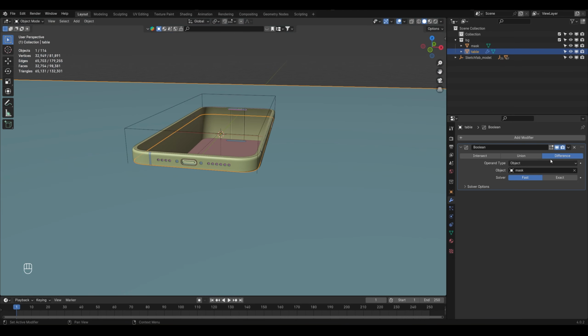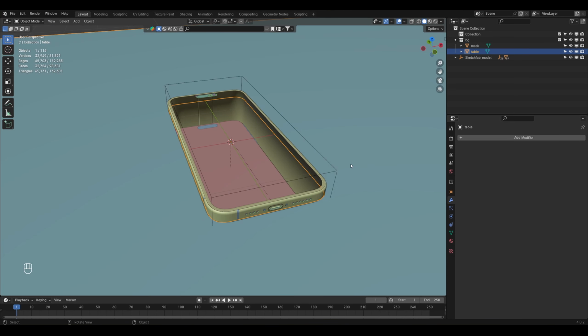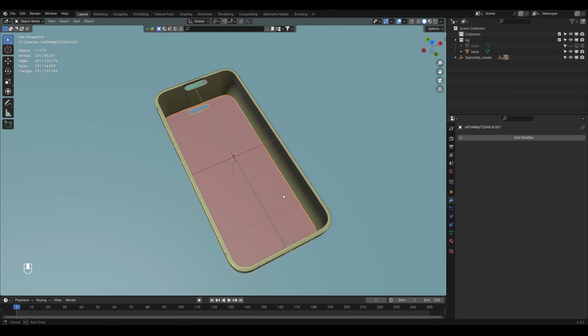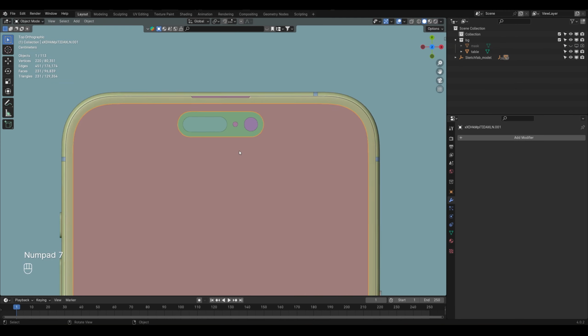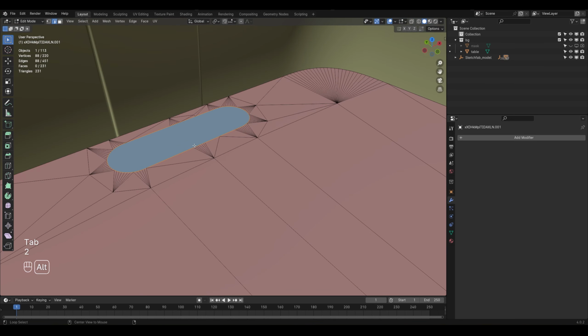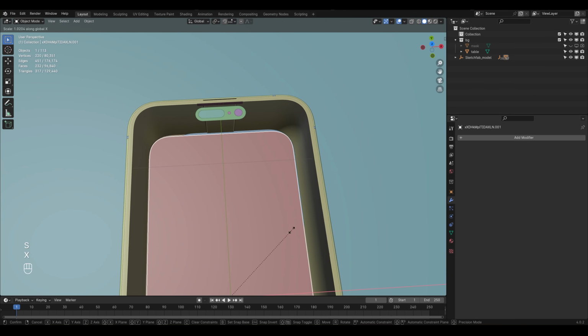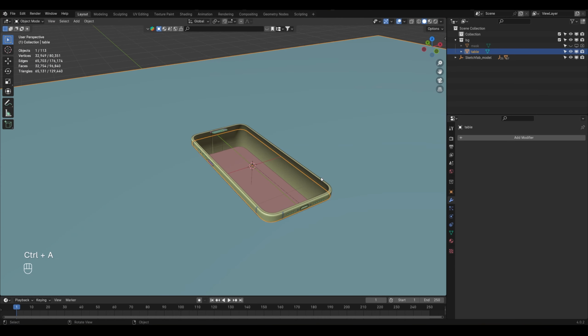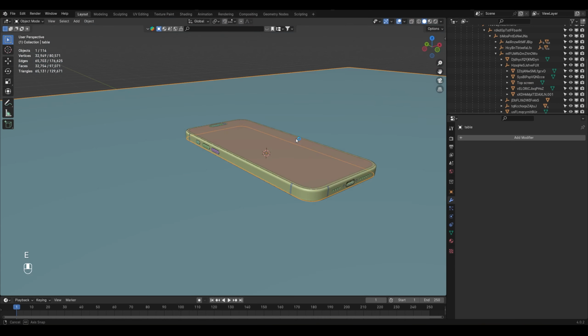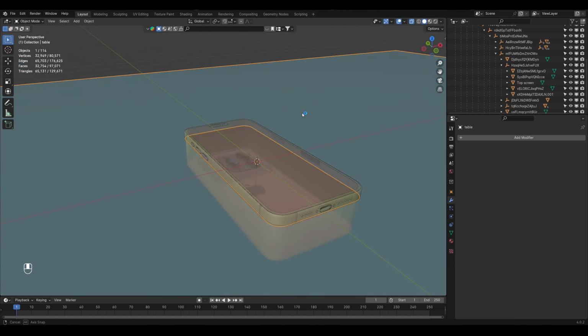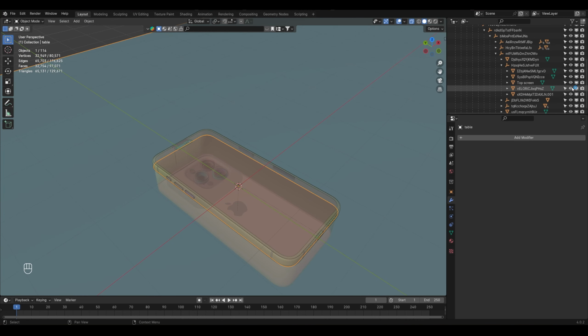And once you're done, you can just apply this boolean modifier. So now we don't need this, but for now I will hide these things. And here I can press 7 and come back, select this and press F to fill this. I also press S, X and just perfect. So now we have perfect space going on, and now we are ready to do the simulation.